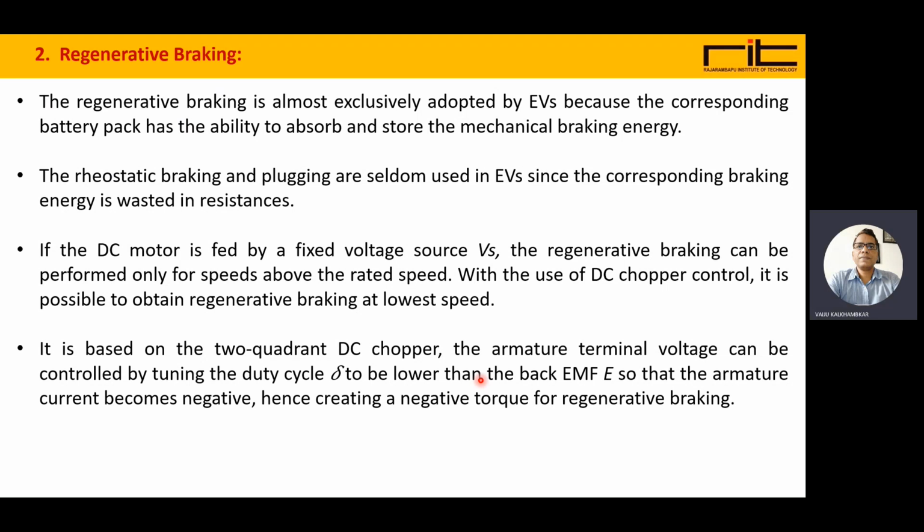Rheostatic braking and plugging are seldom used in electric vehicles since the corresponding braking energy is wasted in resistance. So it is better to use regenerative braking rather than rheostatic braking or plugging.